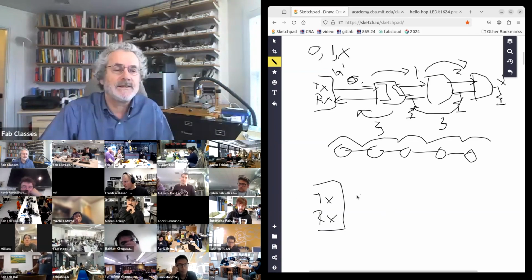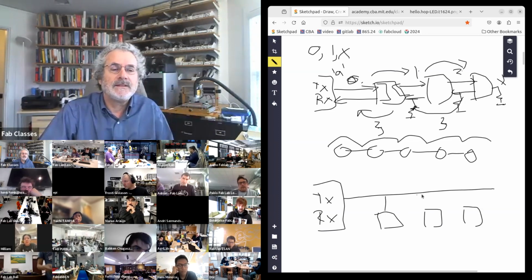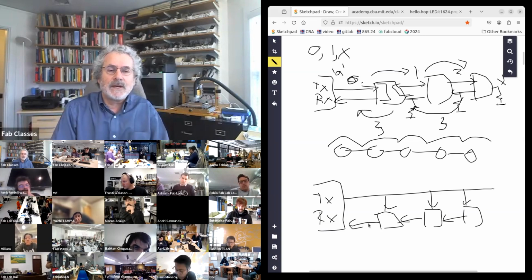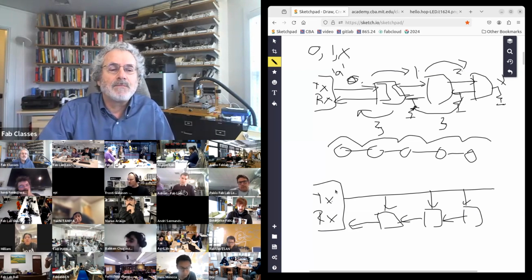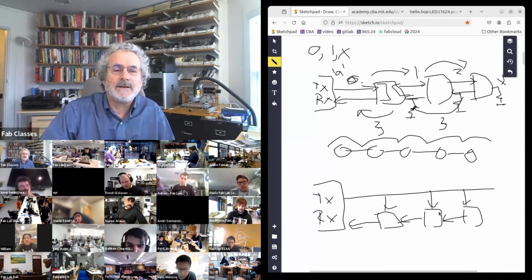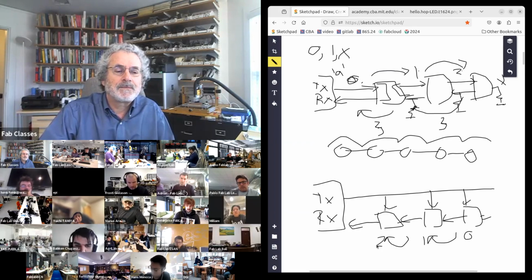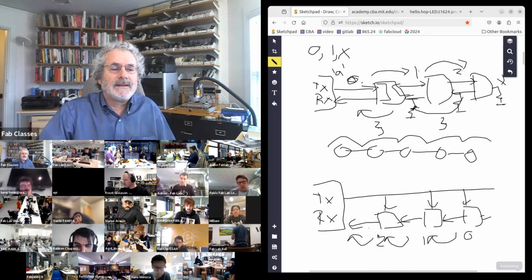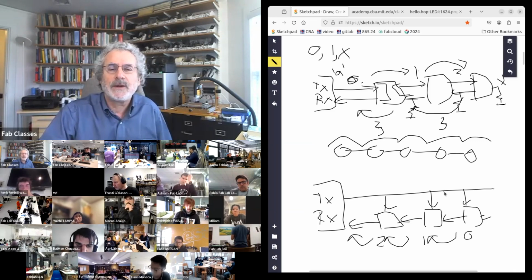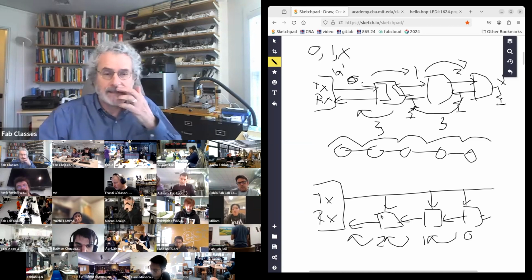The way that one works is I've got a broadcast line that everybody listens to in, but I can locally connect the nodes coming back. So I can send out a broadcast message to assign addresses. This node figures out it's the last node and sends the message back. Then the host can broadcast a message to all nodes at the same time very quickly, but I can use the reverse path to do the address assignment.